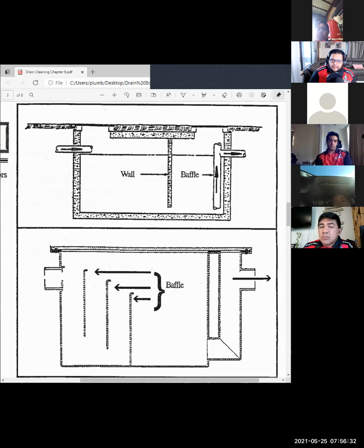You have to, like Josh says, be able to diagnose your stoppage. If you can't see into that baffle and that T where you can't diagnose, you've got a problem to begin with. It needs correction. If there's any of the things in here where you cannot do the diagnostic, get a book, show the owner, this is how it's supposed to be, it needs correction. They need to coordinate a pump truck. When the fluid's out of there, you need to get in there and correct the problem. It's nasty, rotten work, but sometimes that's what we do, nasty, rotten plumbing.